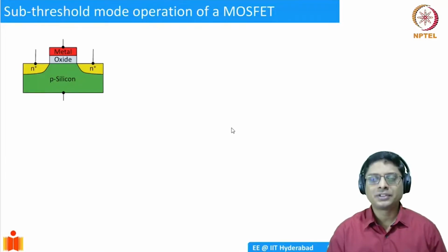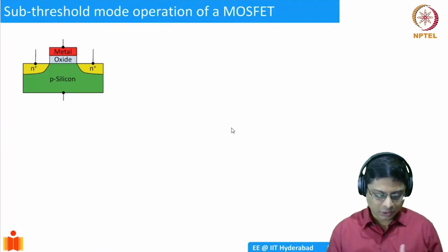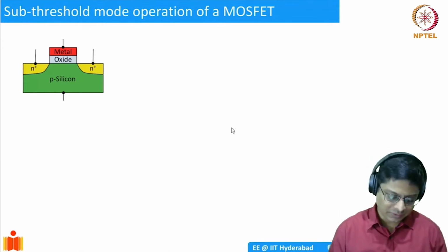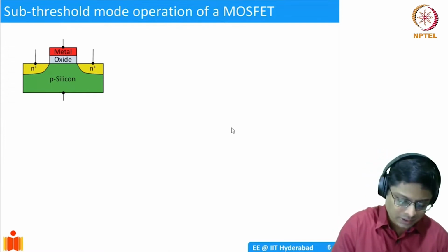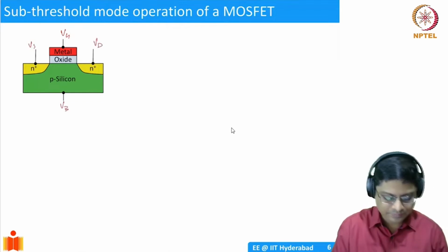Now we would like to talk about the various operating modes of a MOSFET. So we have seen the structure of a MOSFET. Before we talk about the operating modes, we need to label the biasing conditions. So we have these four terminals, and we can talk about the voltage in each of the terminals: gate voltage, drain voltage, source voltage, and bulk voltage.